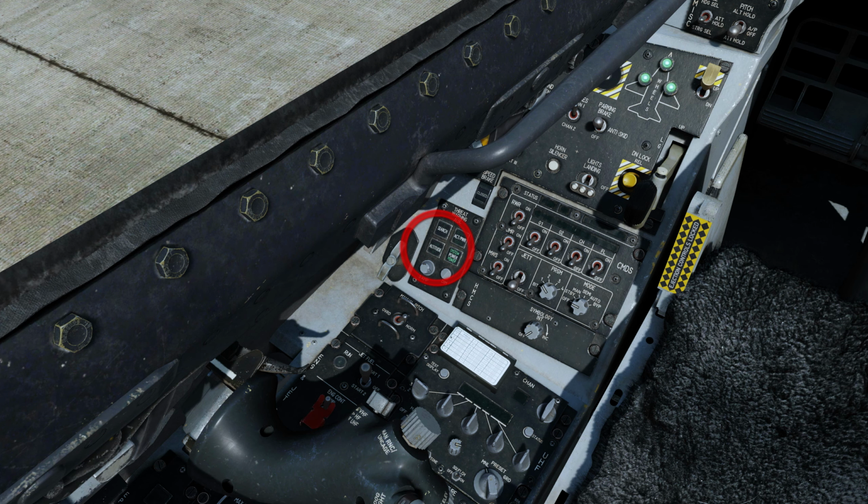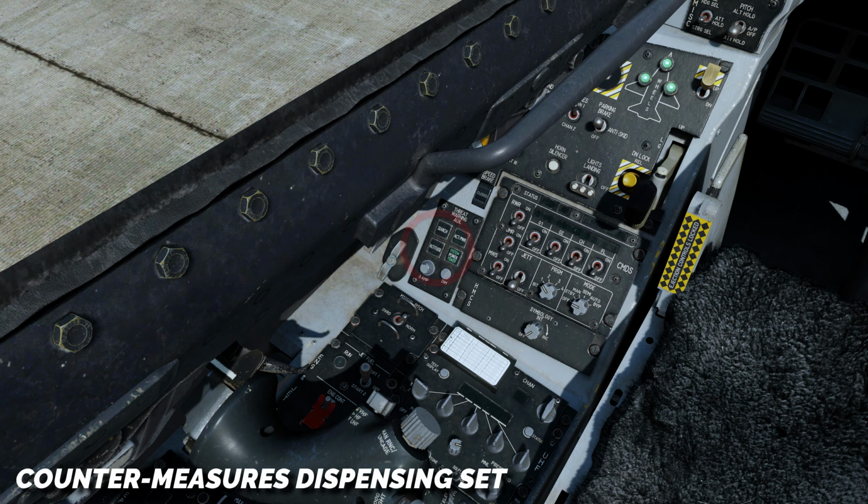The Altitude button toggles between high and low altitude threat biasing, categorizing the SAM threat according to lethality at low or high altitude. High altitude biasing is the default whenever the EWS suite is powered on. Set the CMDS as desired.